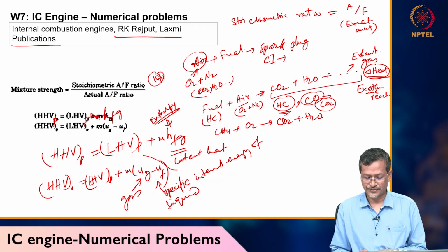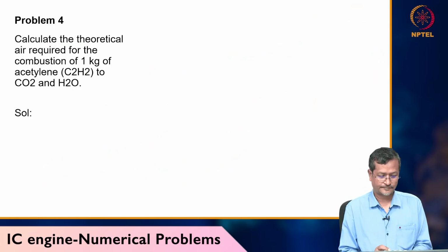In a given combustion process that takes place adiabatically, with no work or change in kinetic or potential energy involved, the temperature of the products is referred to as the adiabatic flame temperature. For a given fuel and a given pressure and temperature of the reactants, the maximum adiabatic flame temperature that can be achieved is with a stoichiometric mixture.